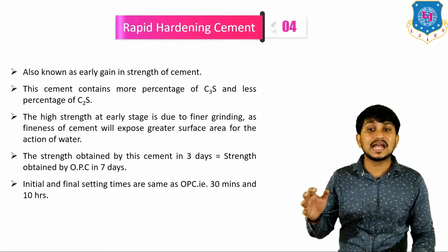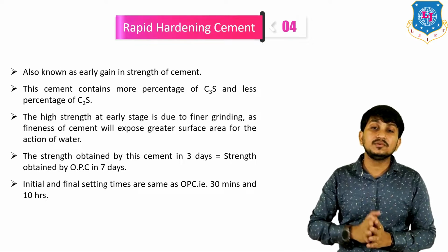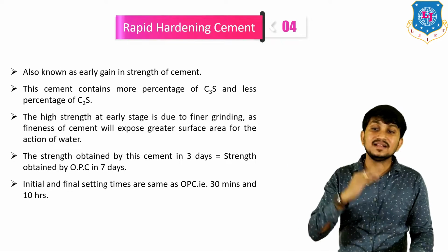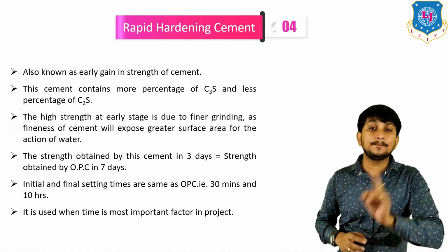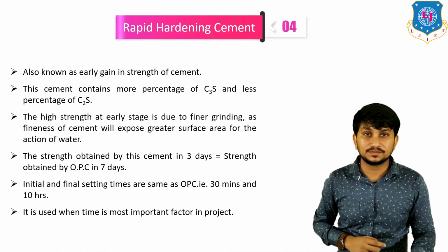Initial and final setting times are similar to OPC, which is 30 minutes and 10 hours. It is generally used when time is the most important factor in the project.